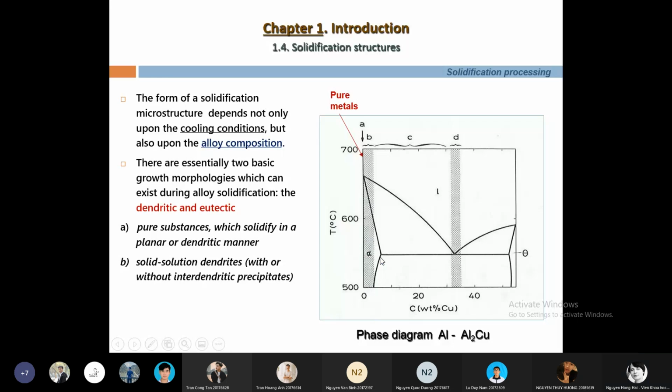Solubility curve. Yeah. On the solute, the alloying element, the alloying atom is in solid solution. Okay. There is no precipitation. This is alpha. You can say it is a wrought alloy. And C, it is dendrite plus some precipitation. Interdendritic eutectic maybe, and maybe some precipitation.